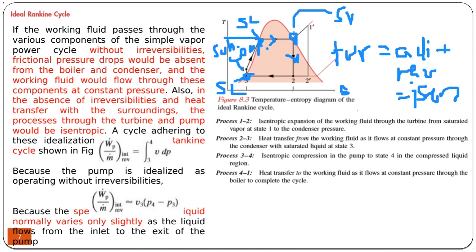On the other hand, it's also possible to heat the vapor further so that you can obtain superheated vapor. In some vapor cycles, there is a section inside the boiler called the superheater, and inside the superheater, the saturated vapor can be heated up to a higher temperature, which is called the superheat temperature.